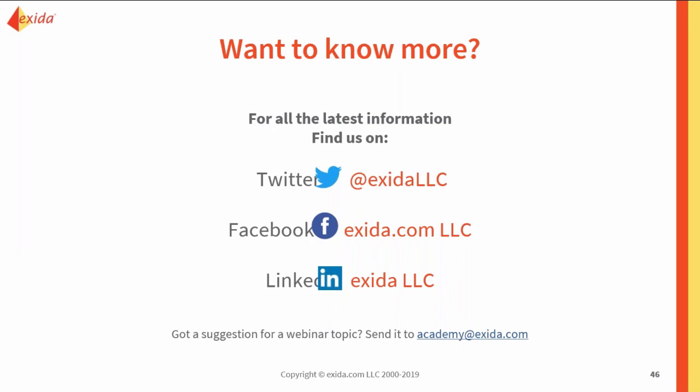For yourself, I would always say use silsafedata.com and check against that as your sanity check. If you do receive failure rates that are overly optimistic, use generic failure rates or those at the top level of silsafedata.com. That would make me feel better and sleep better at night. It might be a little conservative, however, you're not going to be ridiculously optimistic.